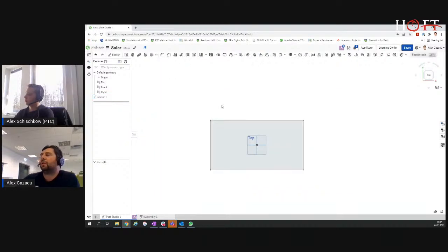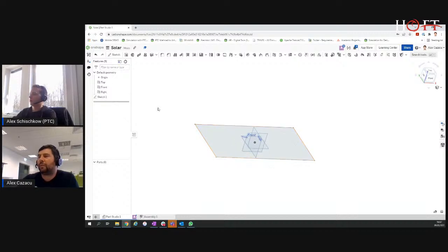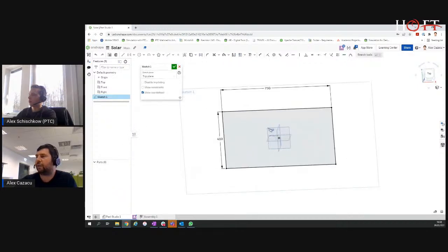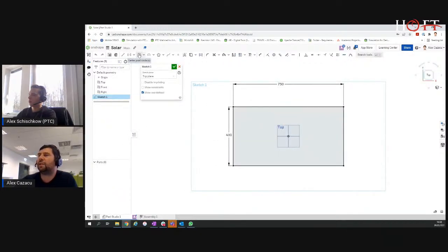Let's go for something like this. Okay, so this will be my first sketch, and let's also add a hole in the middle. I can edit my sketch. I'll hit N again on my keyboard and C for circle, or I can just get the circle from there.